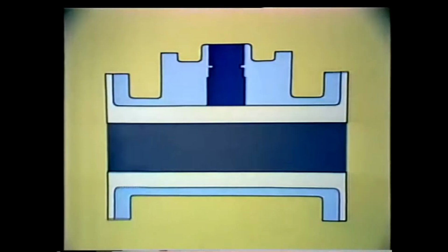Earlier, we talked about the operation and maintenance of a diaphragm valve. Well, let's look at two specialized variations of this type of valve, the pinch and the boot valve. Now, this is a pinch valve. It has a flexible tube which goes through the valve body and forms flange gaskets between the valve and the connecting pipes. The flexible tube is made of a material which has abrasion-resistant properties. Now, this enables the valve to handle and control a flow containing slurries, chemicals, processed food, or pharmaceutical materials.